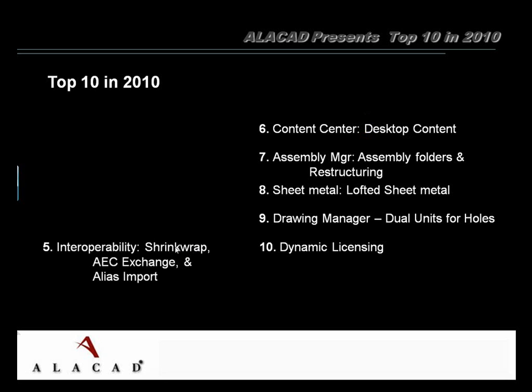Interoperability. I've got shrink wrap actually do shrink wrap. It allows me to take assemblies, fill in what's in between the outside edges, send a lightweight, simple format to people. They don't get my intellectual property. All they get is just the outside model, and then accurately get the outside model.